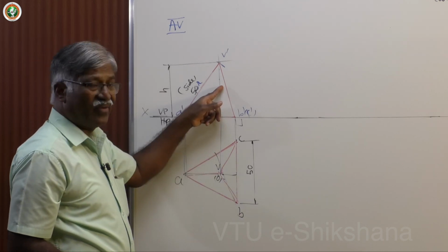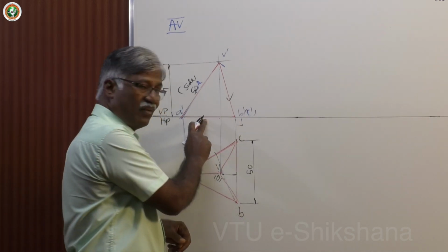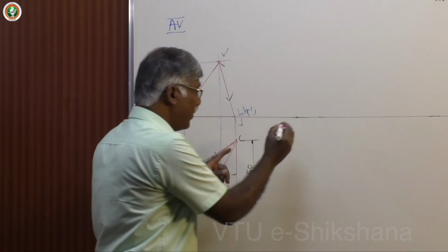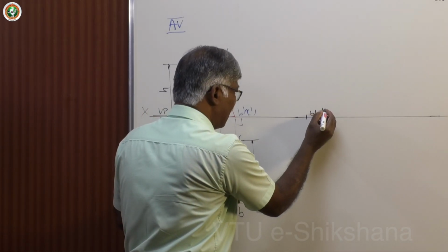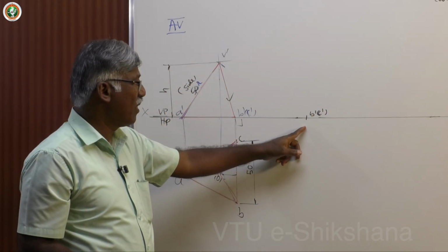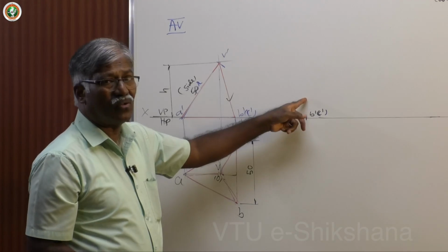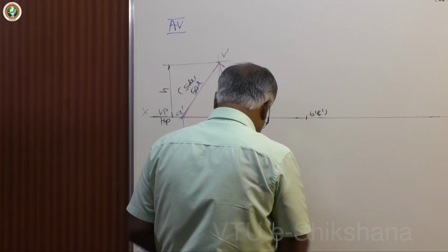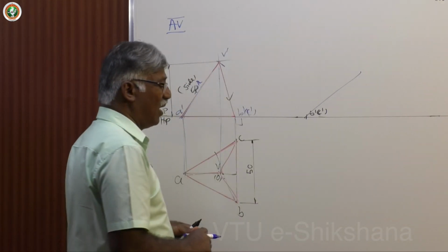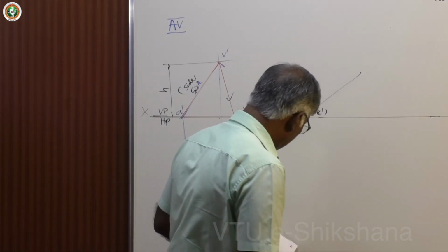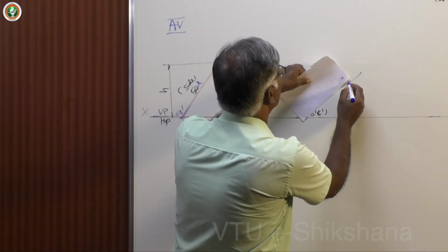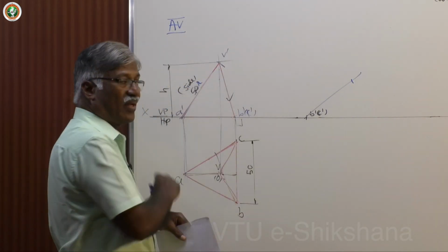Now, this line is important for us, but normally we take the lateral face. Take B1, C1 as a reference. This is the edge on HP or side on HP. With respect to this, you have to draw. Now, let me draw a 30-degree line, and take this distance. Take this distance first and mark. Arc method. You complete this figure.